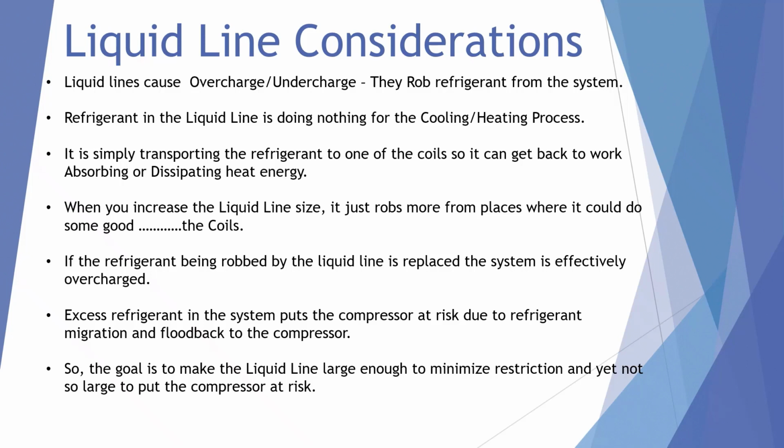Excess refrigerant in the system puts the compressor at risk due to refrigerant migration and flood back to the compressor. So the goal is to make the liquid line large enough to minimize restriction and yet not so large as to put the compressor at risk.